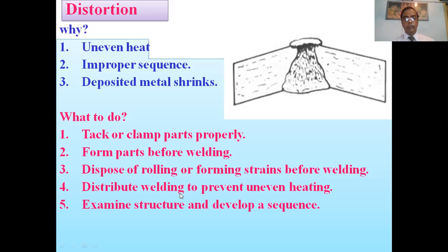Distribute welding to prevent uneven heating. Examine the structure and develop a sequence. So distortion is there, and these are the defects.